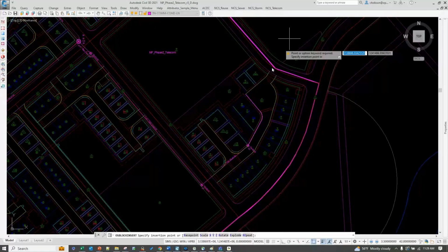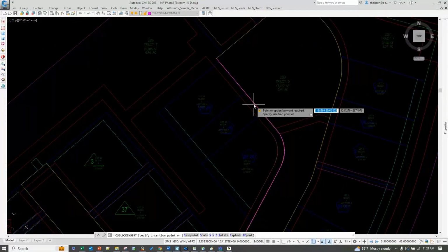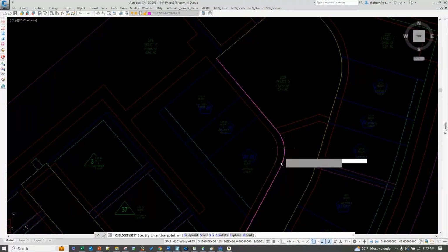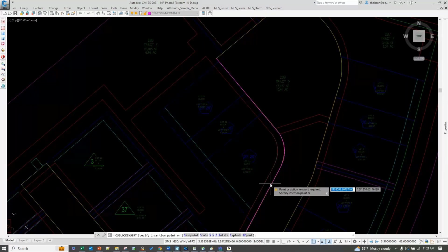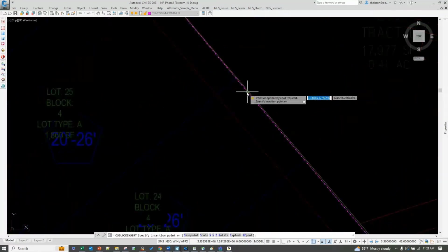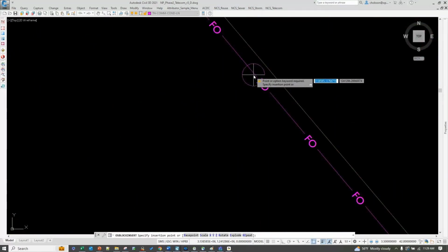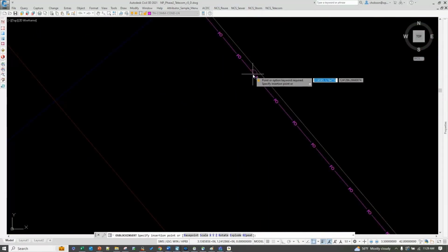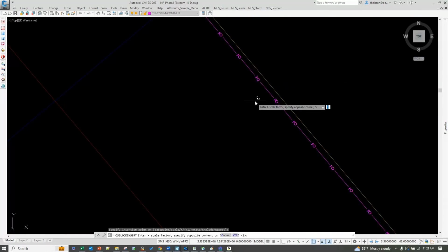So one of the setups was that any midpoint, I could put it there, I could put it in the midpoint of the arc, any midpoint on any segment of this line, I could go in and put that and snap it. You'll notice there's all sorts of stuff there, but let's go find the midpoint on that. Snap it. It's going to ask for scales and prompt you the usual thing when you insert a block.